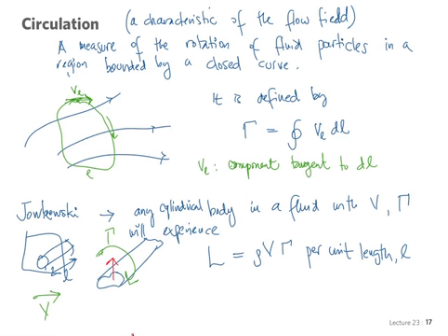Is that a vector? No, gamma is the result of this integral. It's a line integral. So around any curve you measure the circulation inside that area of all the fluid particles by doing this combination. I'm afraid I can't really spend great time to explain where this comes from. I just want to give you a little sort of inkling of what this whole theory is about. You can actually have a whole course on aerodynamic theory that would go into a lot of detail about these things. We're just trying to give you an idea in one class.